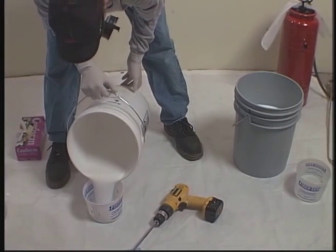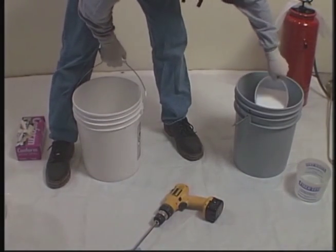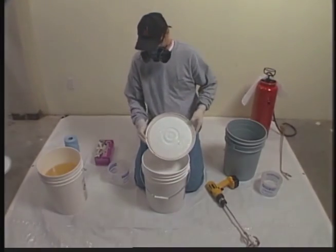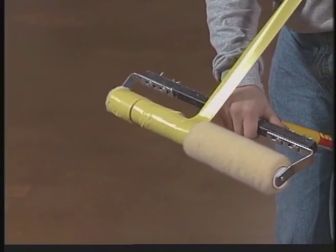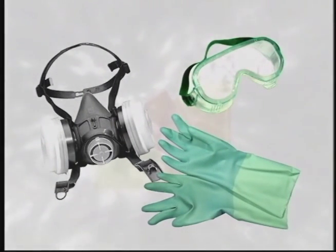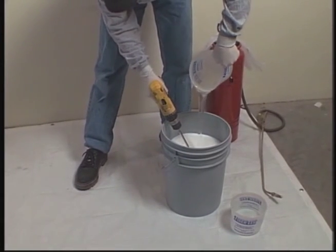Measure multi-component systems precisely and accurately. Follow the test panel formula. Keep containers, lids, and equipment free from contaminants. Remove excess lint from roller heads with tape. Wear appropriate protective gear and safety equipment. All multi-component systems must be thoroughly mixed or blended at the proper ratios to ensure complete homogenization of materials before application.